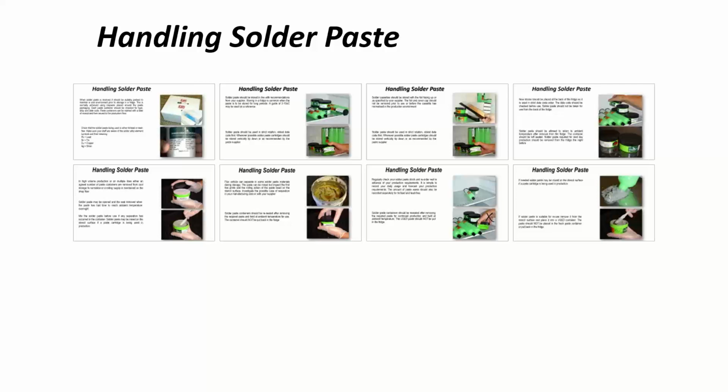Paste that's out, ready for production, it's ready for production. So even if you're not running production for another 4 hours, don't put it back in the fridge. It makes no sense. It's long-term storage. You get a benefit from fridge usage. So when you've got your paste out, you either do a kneading stroke on a printer, or you mix it within the container, which you can't do with cassettes or tubes, but you can do with a jar of paste.